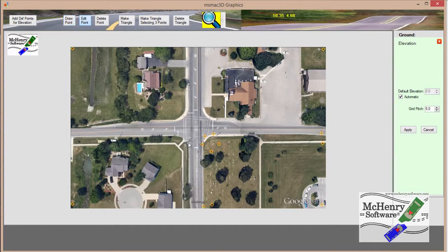Now, next thing we want to do is edit the points. Let's make this -10. Minus in graphics is negative is below the ground, positive is above the ground. In the three-dimensional simulation, it's the opposite, but you'll get used to that. We put -10 for all these. Now the next thing we want to do, so now I've just set these 5 points on the bottom of the ditch to -10. The rest, everything is 0.